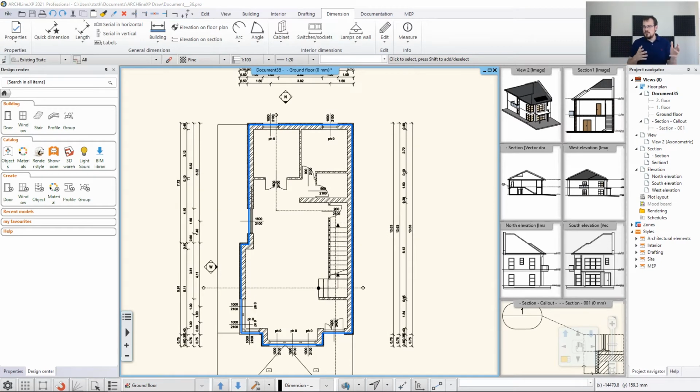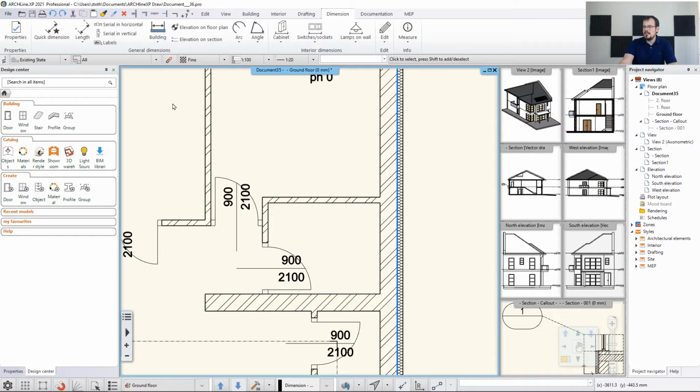In addition to these aforementioned automated tools, there are some manual ways of dimensioning, in case you want to pick something, some precise thing that you haven't dimensioned with the automatic method. You can do it by hand. For that we have two tools. The first I'm going to show you is under dimension, length, and aligned.